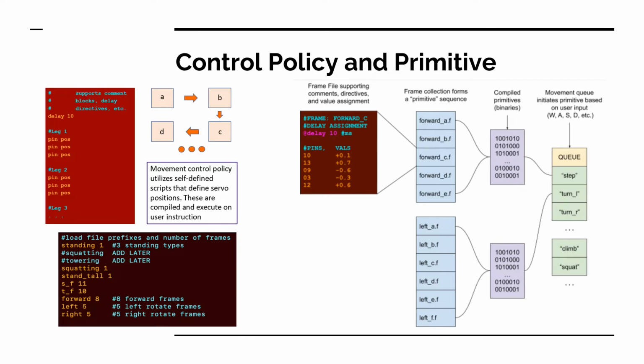By queuing up these basic movements, we can not only ensure that for a broken pipe, that is, broken networking between the user and the bot, we can stop movement very, very quickly at the termination of a primitive. It also means that we can create very complex movement schemes by basically defining patterns of iteration through these existing regions of memory. This is very fast, it's very sparse in terms of stack usage, and of course, the latency is quite low as we intended.